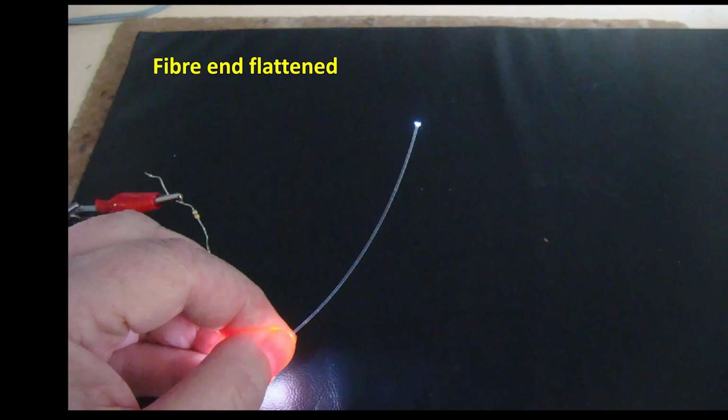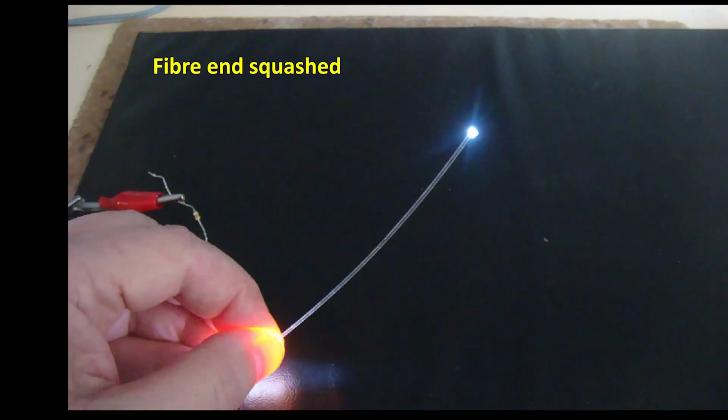I've got a light source between my finger and thumb, and at the other end, I've used a soldering iron to flatten the end. And I get that effect as you see there. If I then put the iron on the side of the piece of fibre and flatten it that way, I get what you see there. So it depends what your use is, how you would handle it. Or you can just simply have it viewed end on for a tiny light.